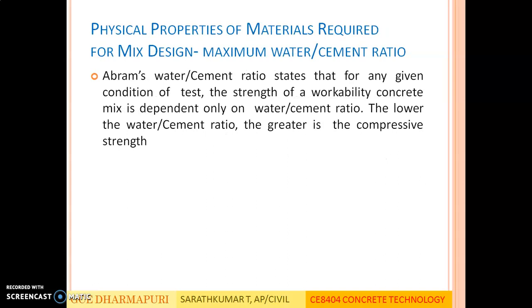Maximum water cement ratio. Abraham's water cement ratio law states that for any given condition of test, the strength and workability of a concrete mix is dependent only on the water cement ratio. So durability, strength and workability all depend upon the water cement ratio. Water cement ratio is the important parameter in the mix design and concrete making. The lower the water cement ratio, the greater is the compressive strength.